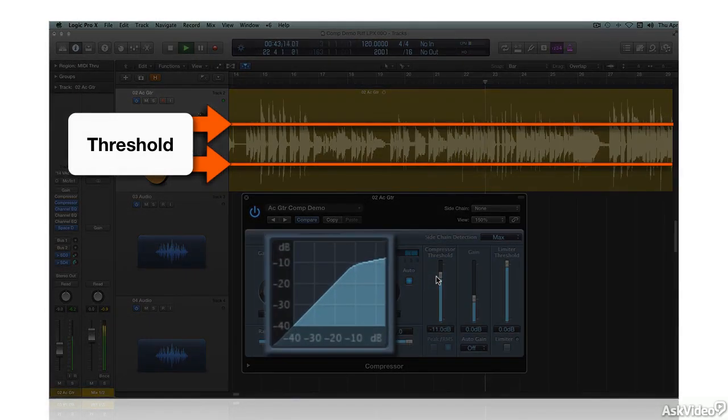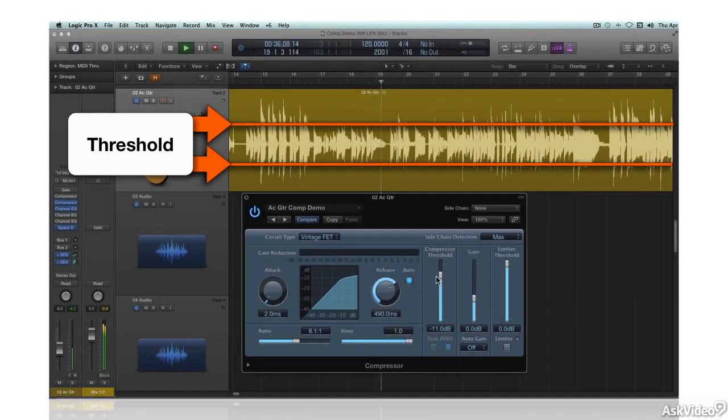Some compressors even have another display that shows the signal level crossing the threshold. This graph is called a transfer function. It shows input level versus output level. No change, no compression applied, displays as a rising diagonal line. Depending on the settings, when the signal crosses the threshold level, that line will indicate the degree of gain reduction dialed up by the other controls. It's good for learning, but most compressors don't include an animated visual with this, so don't get too dependent on it.